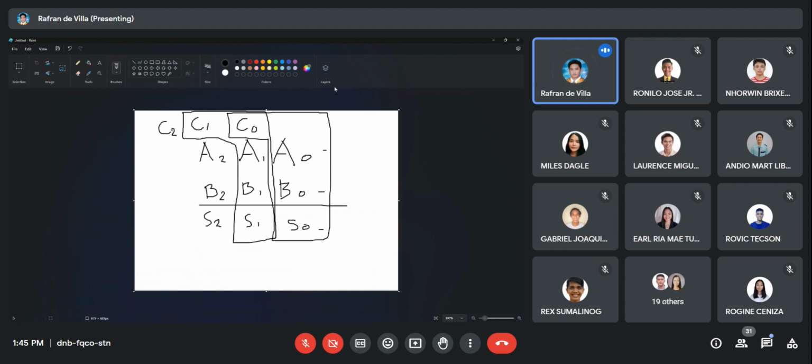So, do you get it, guys? That is why the full adder has 3 inputs. As you can see, if you look closely, you can replicate its circuit so that you'll now be adding 3-bit numbers. If you have another bit called A3, B3, it is easy to extend the design.